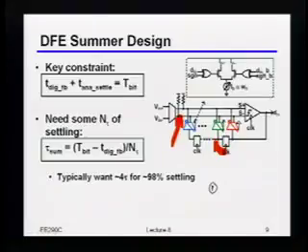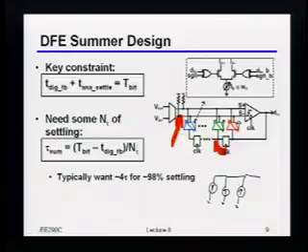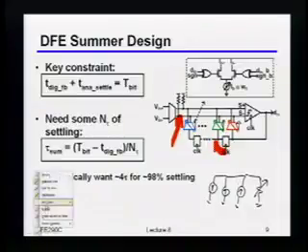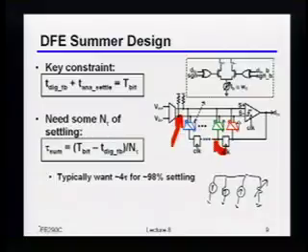So I can take all of those currents and dump them all into some node, but all that nonlinearity is doing is modulating that resistance, right? So in other words, the addition itself, because that's all happening in the current domain, is linear. The only thing that's nonlinear is converting it to voltage afterwards, which means that the coefficients are also actually correct.